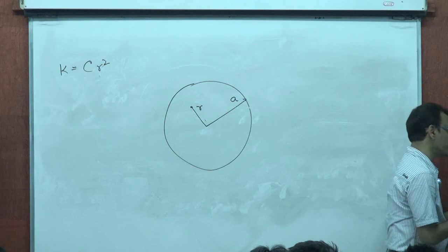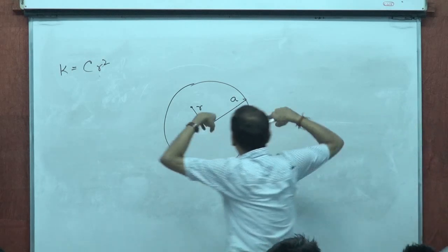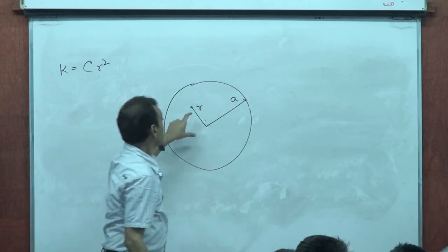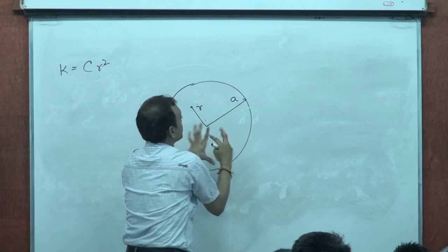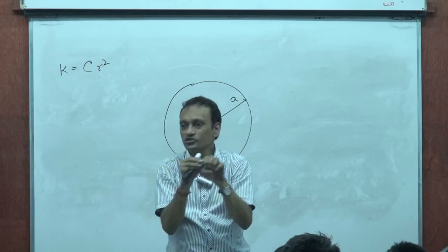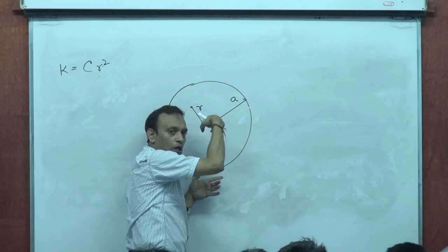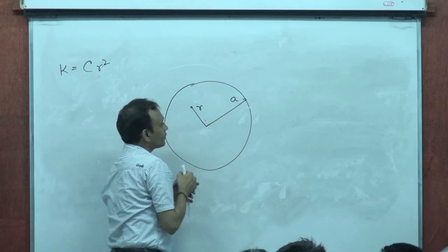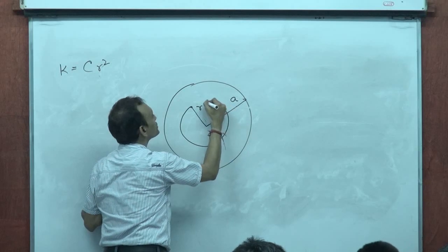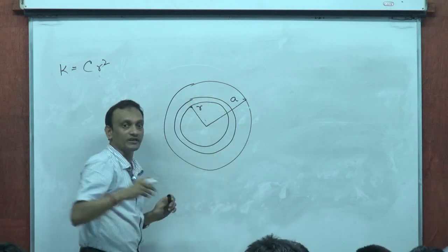Now, one thing, this is not radial flow of heat. This is longitudinal flow of heat, but the thermal conductivity in a given cross section is varying with r. You know, this could be a complex material whose thermal conductivity is varying in r. The flow of heat is still longitudinal, right? You know what I'm saying? Now, I want to find the temperature gradient in this. If H is the heat current associated.